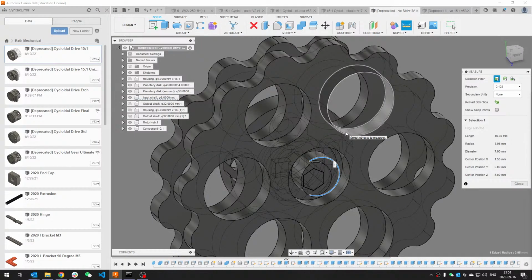Okay, let's see. So this one is 8. So increased by 6, we got 14. 14 inner diameter. Okay, I have 18 by 12 by 4, so that's not enough. But if we decrease the eccentricity to 1, the difference will become like 2 millimeters. So 8 millimeters plus 4, we got 12, which works.